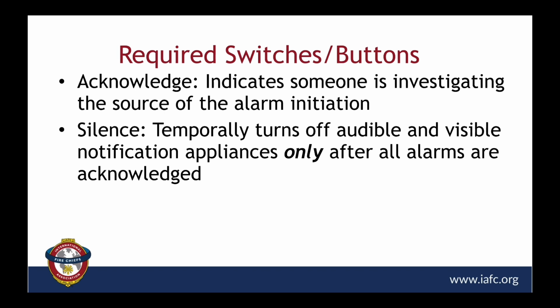And when you're in silence mode and another detector or water flow switch should be activated, these systems by code are required to reactivate. So don't fear if you silence it that you're shutting off the whole building per se. Yes, you're silencing the building. That's why the word temporarily is there. But if that fire should start to grow or is detected at some other point, the system will completely realarm and reactivate. Next slide, please.